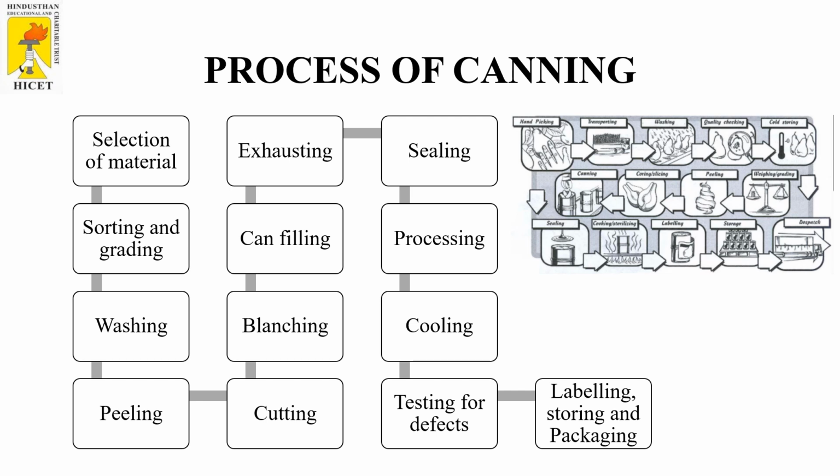Next, coming to the sealing process, which is sealing or closing. Immediately after the exhausting process, the cans are sealed by using a double seamer, where this double seaming is a two-step operation. In the first operation the can lid is inserted on the can body hook by holding and rotating the lid in position between two rollers. This operation is called clinching. The next step is to press the seam using the second operation roller, which results in an appropriate overlap of the body hook and cover hook, which results in an appropriate countersink.